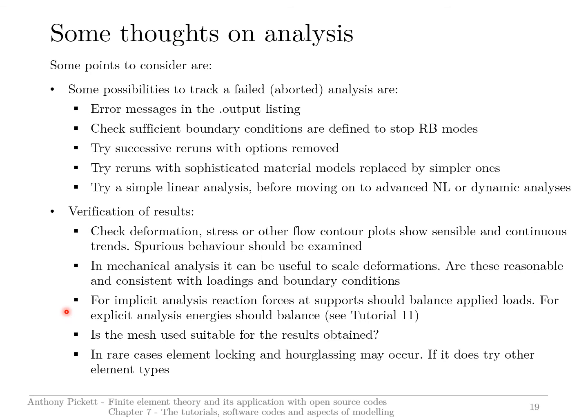In rare cases, you might get some kind of lock-in phenomenon, or more likely, especially in an explicit analysis, you might see hourglassing taking place, where you get a very strange shape to the mesh.